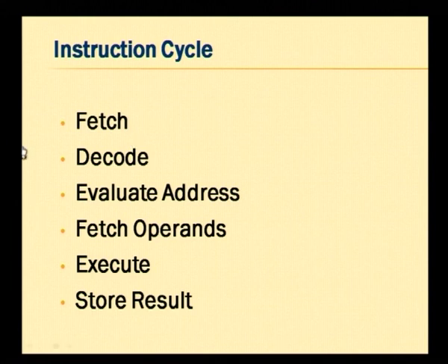And second, I will have to decode that instruction. What do I mean by decode that instruction? We just saw that an instruction has a particular format. You will have an opcode, and it will have various details that are specified. So, we need to know what is the register that I need to operate on, what is the opcode, what is the operation to be performed. You need to understand that instruction. That is what we mean by this decode operation.